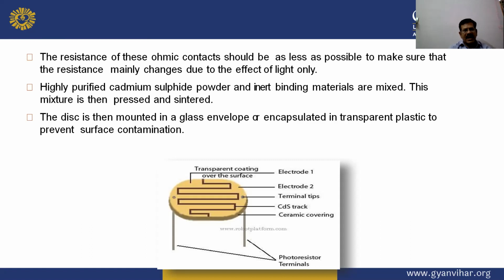Highly purified cadmium sulfide powder and inert binding materials are mixed. This mixture is then pressed and sintered. This disc is then mounted in a glass envelope or encapsulated in transparent plastic to prevent surface contamination.